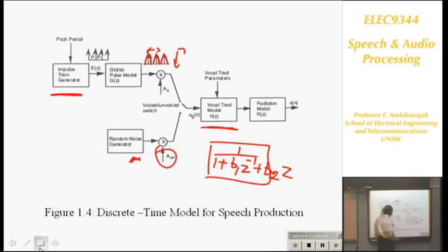You've done this properly. And you can analyze, and this filter has got a resonance. It will give you one resonance frequency. So if you've got 3 resonance frequencies, you must have a 6th order filter. One second order section gives you 1 resonance, another gives another resonance, and a 6th order filter is the minimum you need here, but normally you need more than that.